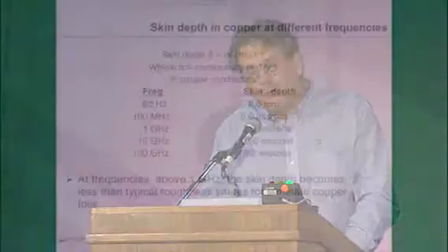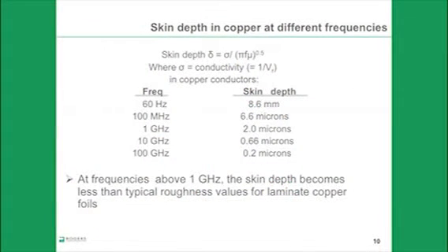If you're attending IMS, I'm not going to be able to tell you anything about skin depth that you don't already know. The only reason I put up this slide is to remind you that at frequencies of about 1 gigahertz, the skin depth becomes less than the typical roughness value for laminate copper foils.